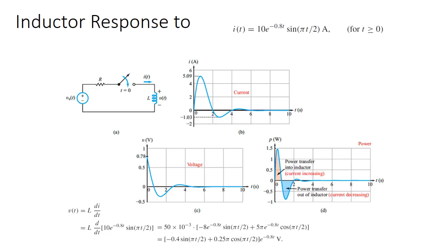So if we look at circuit A, we're going to see our RL circuit, which is what that equation comes down to. We have a voltage source, a resistor, and a switch that's going to switch on exactly at t equals 0. I'm going to get to why that's important. Once that switches on, we're going to have the current i(t) flow through our inductor.